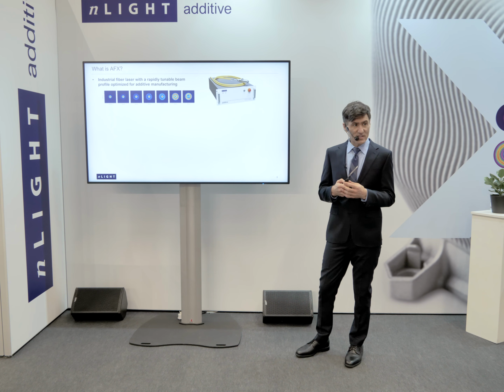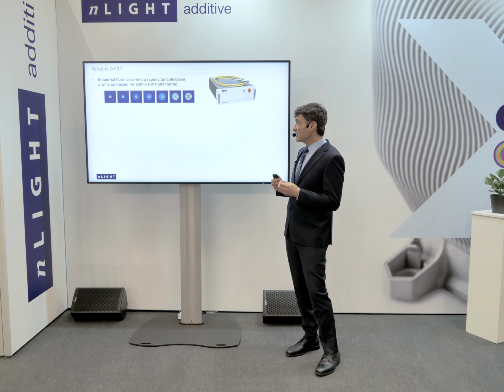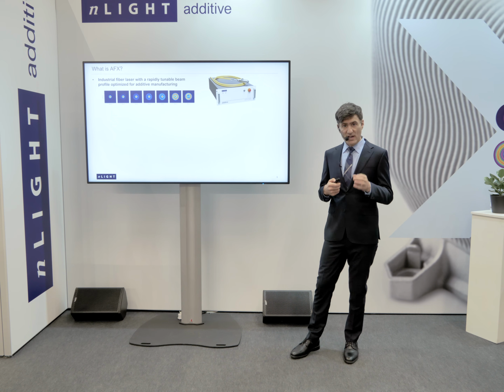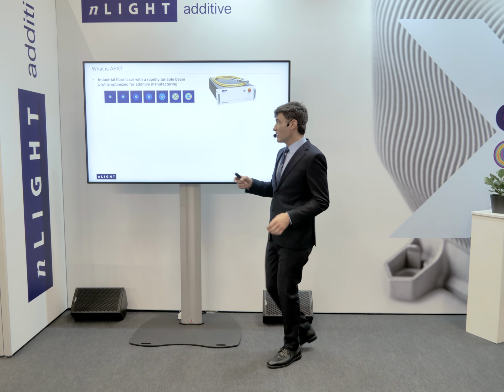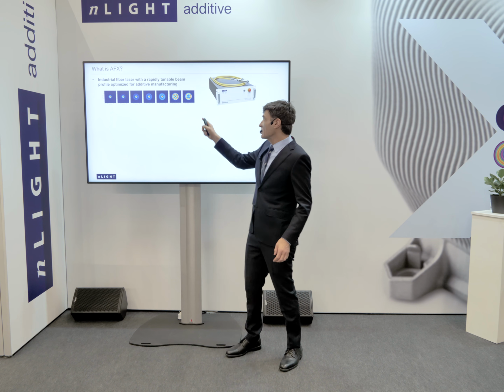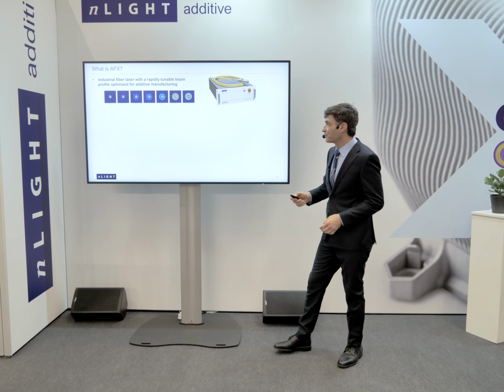So, in a sentence, what is Afx? It's an industrial fiber laser with rapidly tunable beam profile that's been optimized for additive manufacturing. So the beam can be adjusted from a standard single mode 14 micron beam here to a 40 micron ring shaped beam and all shapes in between.